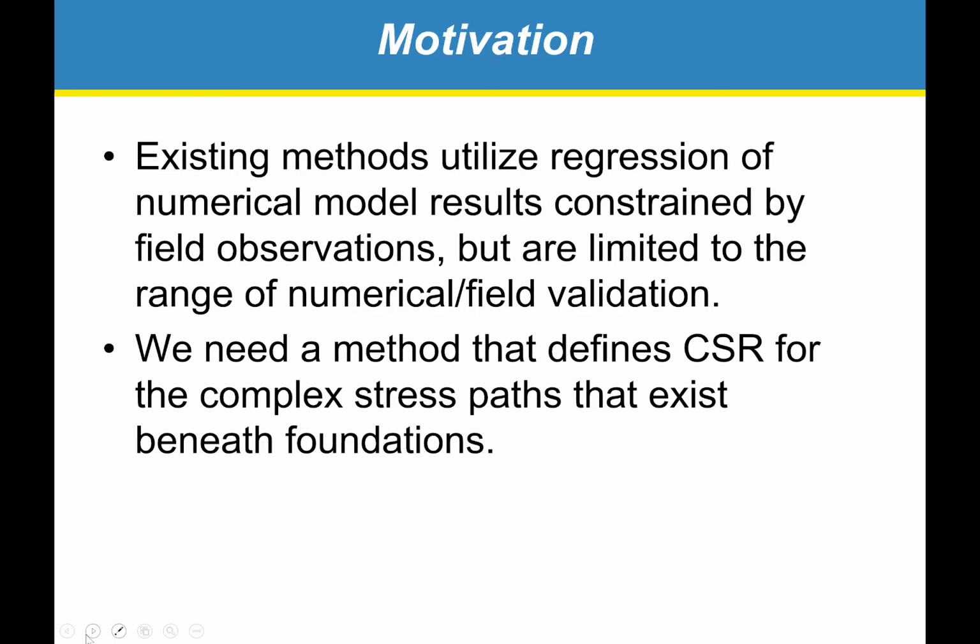Our method is focused on whether failure is going to happen at a point, so it's more like a triggering analysis or a cyclic softening analysis that we do for a one-dimensional soil column. So we need a method that defines CSR for the complex stress paths that exist beneath foundations. We have it for one-dimensional propagating shear waves. We don't really have that yet for the complicated loading conditions, and that's what I'll present today.